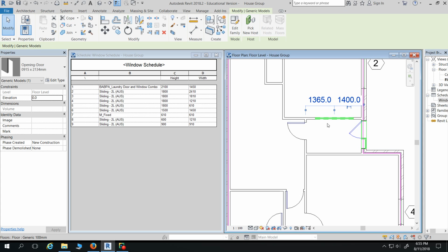Eventually you get to a point where if something does move a little bit, you'll be fine, and I'll just move it back. But at this early time in learning Revit, if you go too far down the garden path, it can be quite difficult and annoying to fix something. That's why I always suggest you reference a 3D view. If you put all the windows in, check your 3D view just to make sure they're all right. Just like your wall heights when we drew it last week, check your 3D view to make sure it all looked in proportion and it wasn't 8 meters high because you missed a step to say it's connected to the first level. So it's that sort of thing.